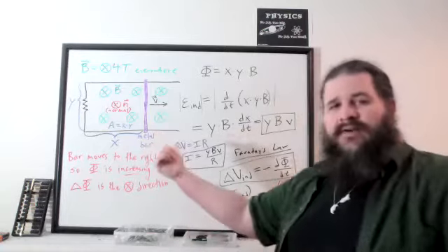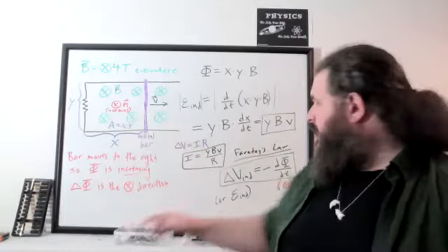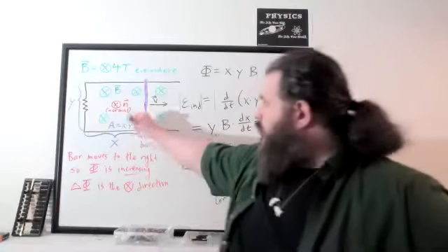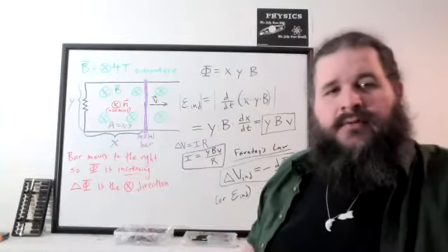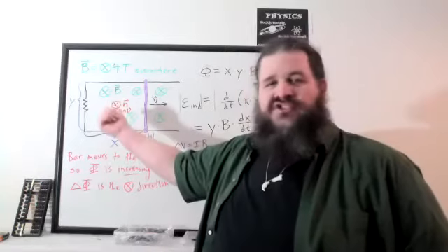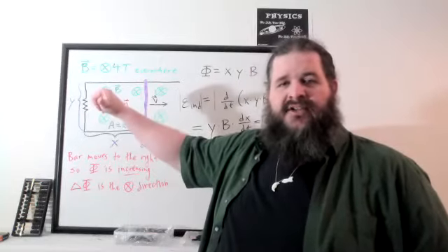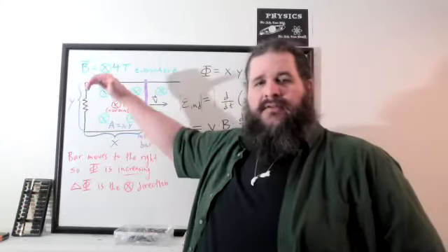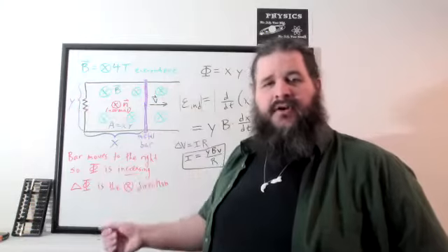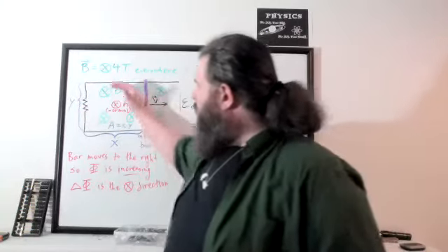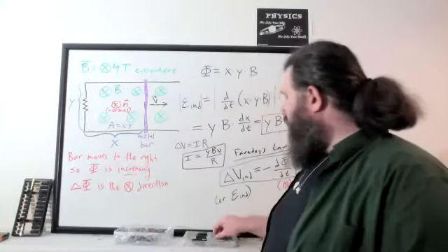The negative sign in Faraday's law reverses that, so the overall result, the voltage, would be associated with the outwards direction. Of course, nothing's flowing outwards because that's not the direction the wire's pointing, but you can use the right-hand rule. Inwards change, reverse because of the negative sign, so point your thumb in that reverse direction, and the curl of your fingers of your right hand suggests the direction of the current. So current is going to flow in this direction. We describe this in this case as counterclockwise.